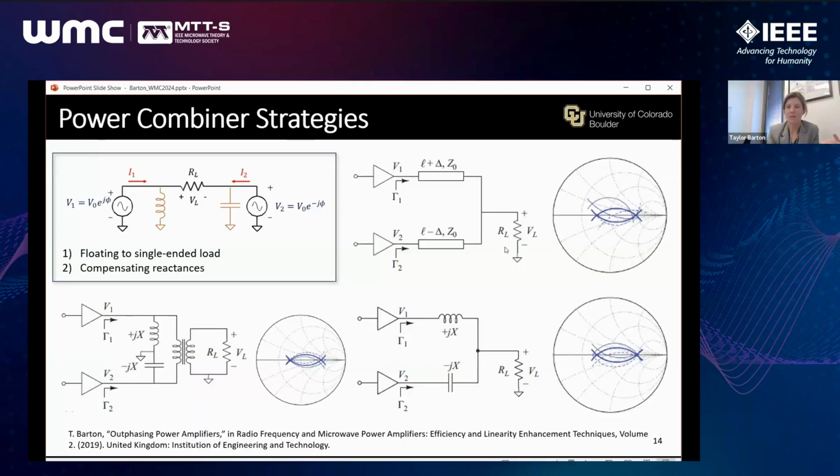The PA I want to tell you about first is an X-band MMIC, and we actually ended up using this quarter-wave line structure. We considered the lumped element structure, and I have seen some work that does that. But when you're working in an MMIC, as many probably know in the audience, your tolerance of your lumped elements can be pretty bad, right?